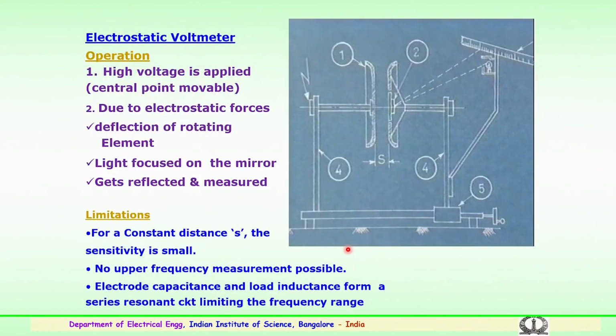So this is the typical arrangement of the electrostatic voltmeter, which consists of an assembly consisting of, as mentioned, the two arms of the electrostatic plate type of arrangement here. So you have an indicating scale, and a small mirror which is here, because of the electrostatic forces which we developed. This mirror reflects, and this is indicated on the scale. This is how the simplest measurement is being done by using the electrostatic voltmeter.